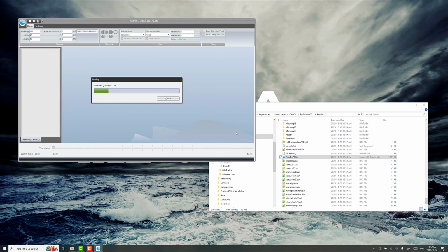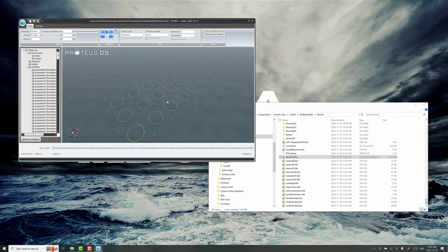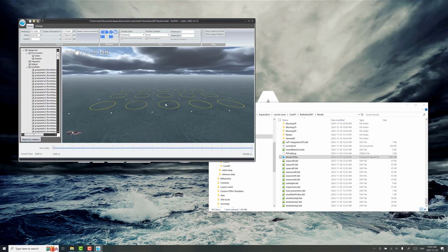It's always good to spot check these results. It can be tricky and easy to make a mistake in terms of file output, or having an incorrect current speed, or not turning on the waves when you get to the wave loading analysis. So it's always good to do a visual check. You don't have to do it on every single one of them, but it's always good to check your work this way. You can also peek at the results as they're progressing through and see how things are going, and to save time as well.